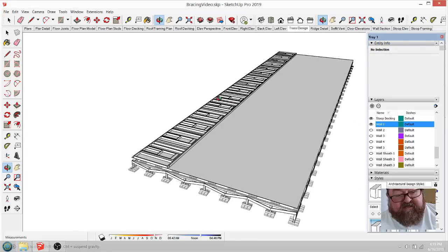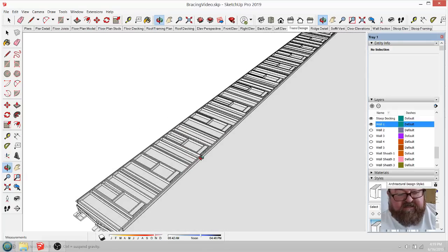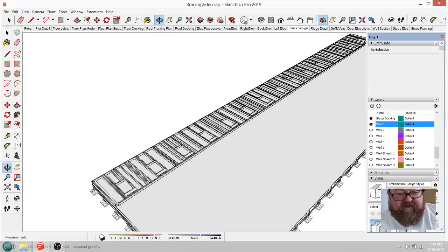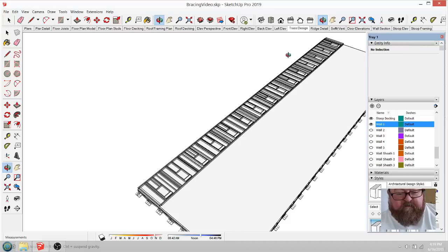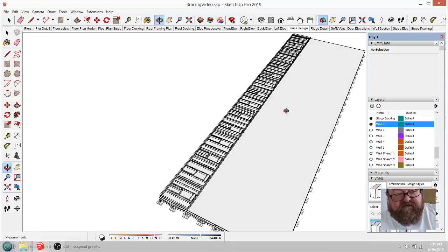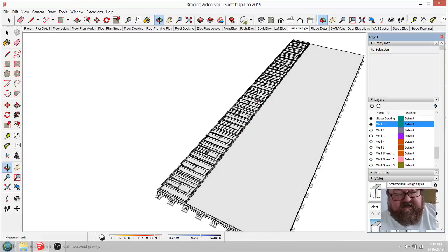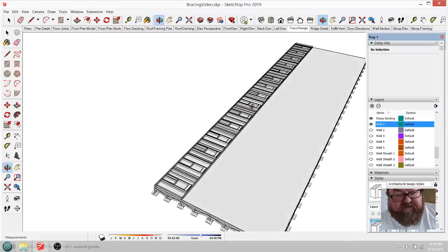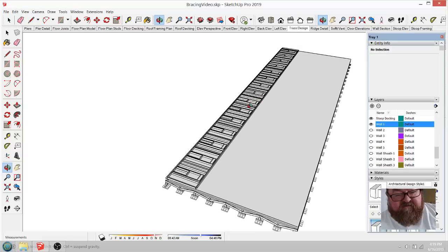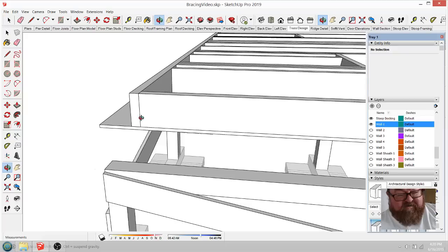Let's pretend it's laying on the floor, and we've got a bunch of guys. Honestly, on a wall like this, you might even break it up into 3 or 4 sections, maybe 3. You wouldn't necessarily want to build a 108-foot wall all in one section. That goes to the point about temporary bracing: even if you built this wall in 2 pieces, you would want temporary bracing to stand it up and brace it off while you're standing up the other half. But for the sake of this discussion, we're not having an argument yet, are we?